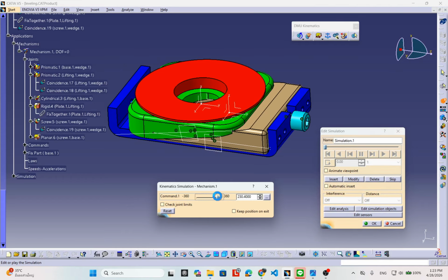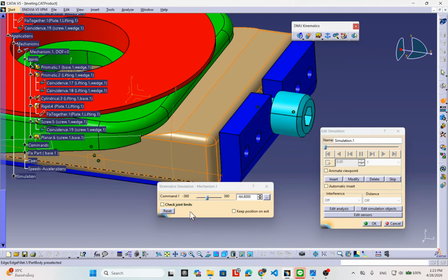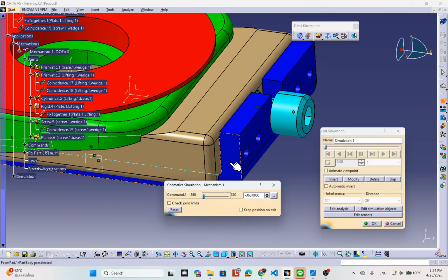Hey, move right here. Okay, here. You see here. Like this. Right, but the length is not enough, right? It's one round. One round is 1 millimeter because one round, the move relates to the pitch distance. The pitch distance is 1 millimeter, one round moves 1 millimeter far away. That's it. That means you must calculate.